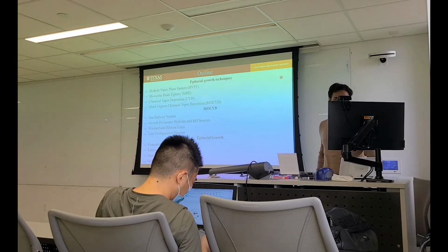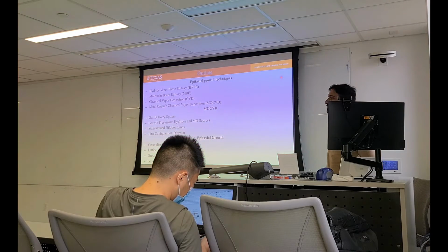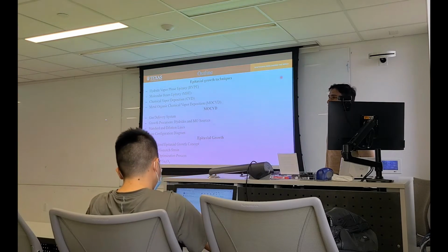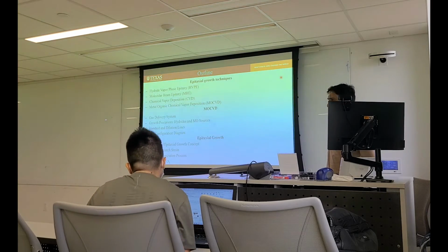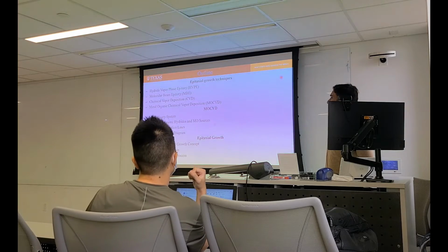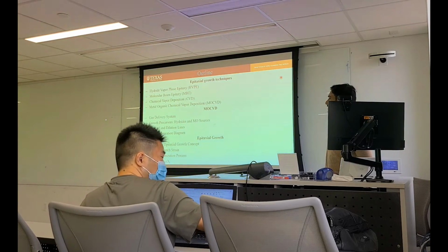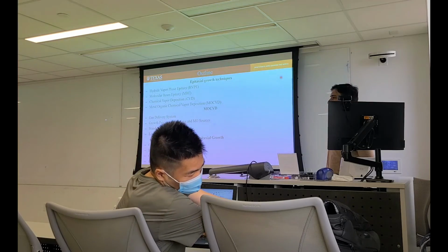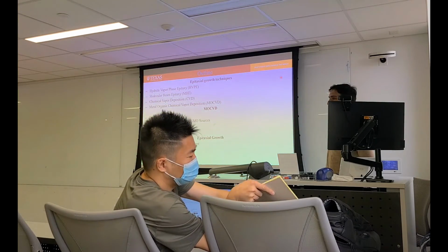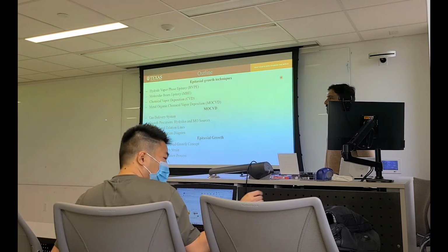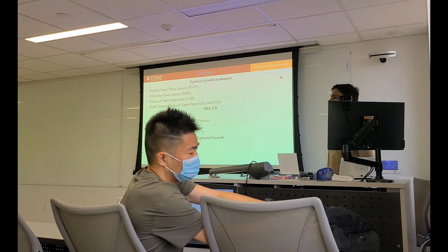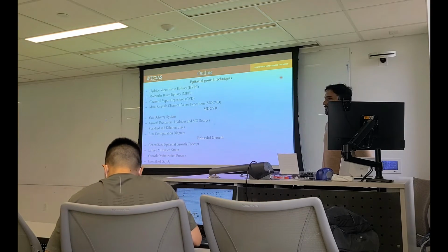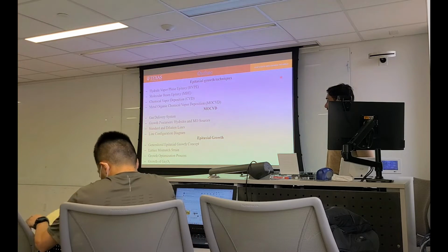In my lecture, I will briefly talk about the epitaxial growth techniques. So I believe you know basics about hydride vapor phase epitaxy, HVPE, MBE, CVD, and MOCVD. I will extend my discussion on MOCVD. I will talk about its gas delivery system, growth precursors, hydrides and amino sources, standard and dilution lines. So, did you know about dilution lines? Did you study about that? Okay. And then line configuration diagram. I will show that diagram here.